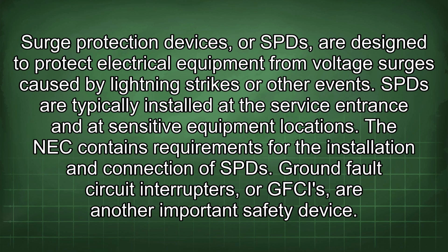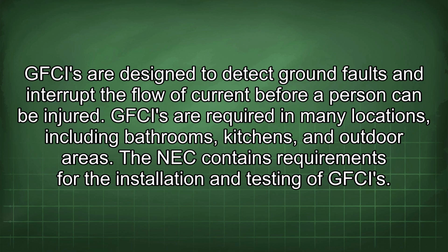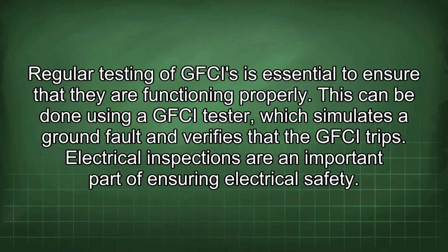Ground fault circuit interrupters, or GFCIs, are another important safety device. GFCIs are designed to detect ground faults and interrupt the flow of current before a person can be injured. GFCIs are required in many locations, including bathrooms, kitchens, and outdoor areas. The NEC contains requirements for the installation and testing of GFCIs. Regular testing of GFCIs is essential to ensure that they are functioning properly. This can be done using a GFCI tester, which simulates a ground fault and verifies that the GFCI trips.